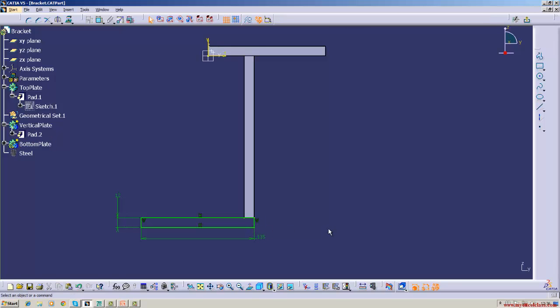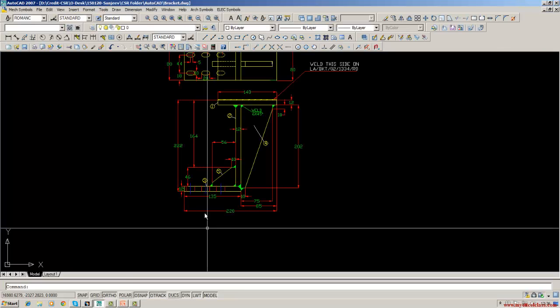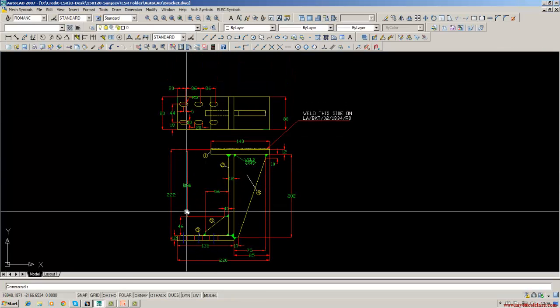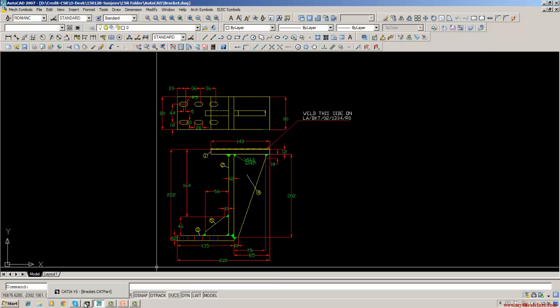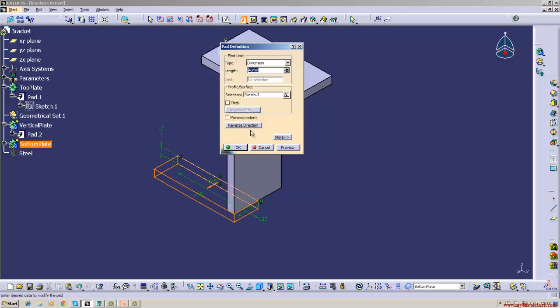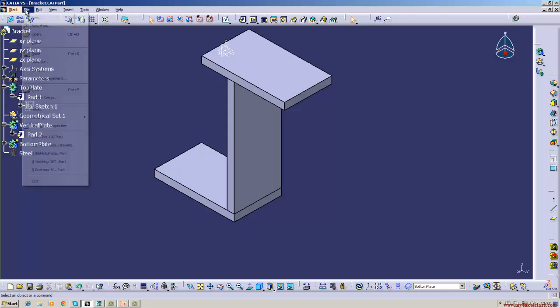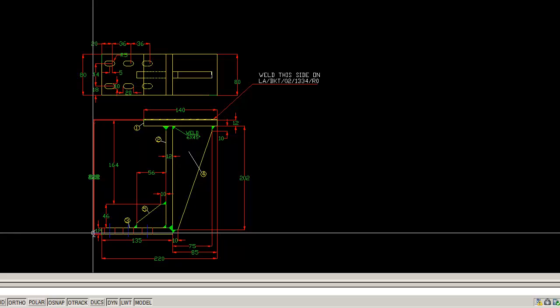If a line is projected extra, you have to trim it by using this command. Okay. Now this is 12 mm. Now you come out of the sketcher plane. This is also at the center, and how much it is projecting around on either side. This is also 80 mm. That is the mirror extent. So 80 mm. Select pad. It's 40 mm. Mirror extent is 80 mm. Okay. Now part of the bracket, I should say, is created.